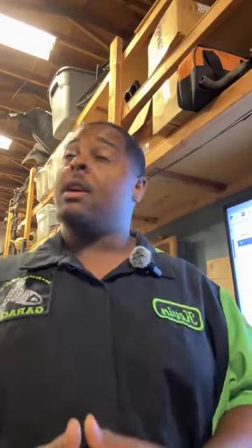So, sorry, I'm getting off my soapbox here. Go with quality parts. They don't have to be OEM. Get the whole assembly. Avoid issues in the long run. But I feel like your issue is fuel delivery, fuel volume. If you want to just start from square one, the cheapest, quickest way, change your fuel filter.